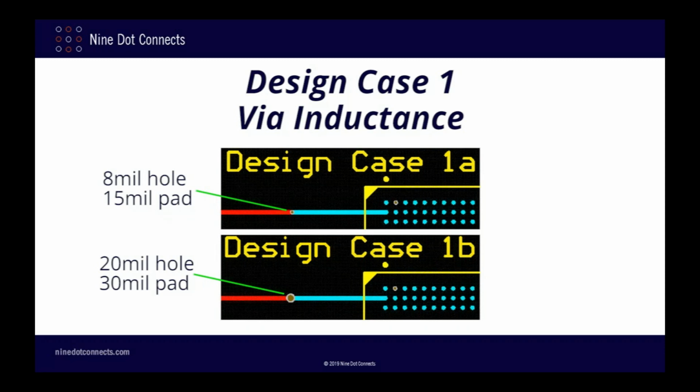Right away, we can safely assume that the signal integrity will change and probably get worse, since we now have a mismatch between the impedance of the trace and the impedance of the pads. In addition, by enlarging the via pads, we have effectively added a capacitor to the trace, formed by the pads and the PCB dielectric itself. And yes, as the questioner pointed out, we have also changed the inductance of the via itself.